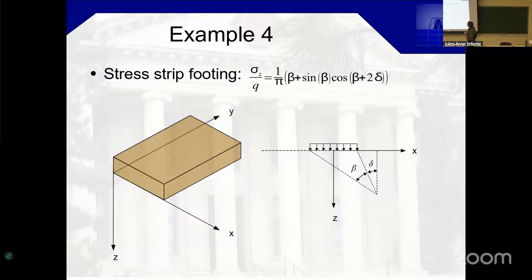With that value, and excuse me, why do you take it like the point? I'm just using the elastic, this is based on Boussinesq elastic theory, right? We're not going to do the calculation of the stress change with depth, because before, we assumed a very wide loaded area and we had 10 kPa increase everywhere.